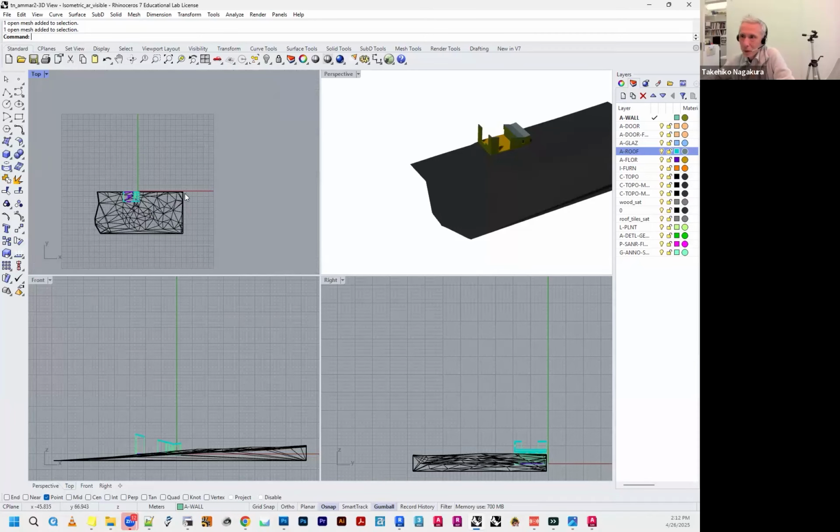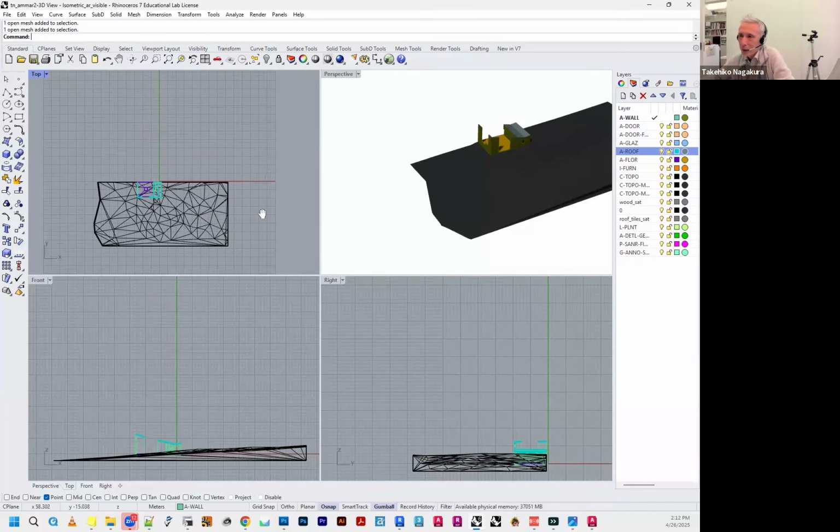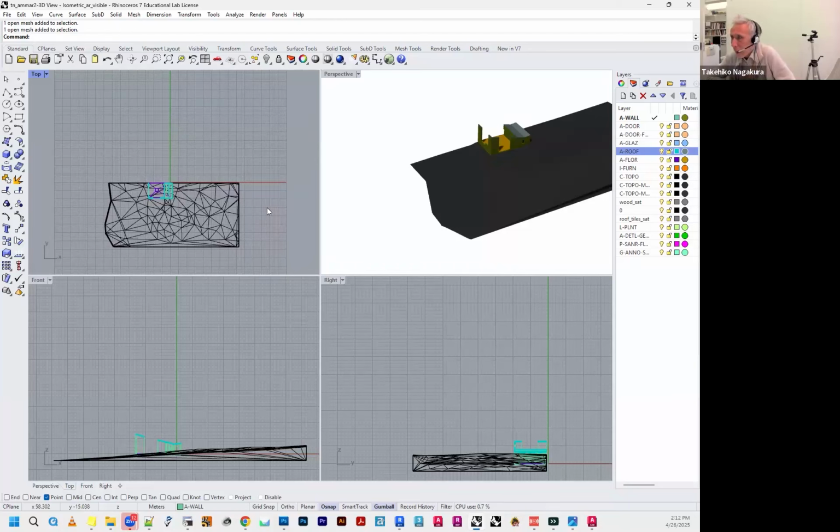The reason you want to check it is that in the end, in the Design Heritage platform, the platform is adjusted so that by default, if the model is within about a 100 by 100 by 100 box, the adjustment you need to make will be minimum. If it's much larger or much smaller, you would need to do a lot of adjustment. So the rule of thumb is to make your model fit in that box of 100 by 100 by 100 units.